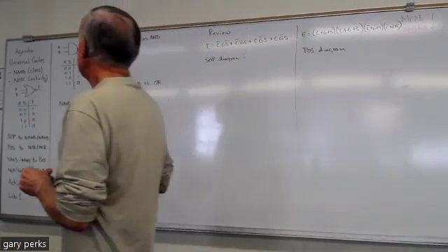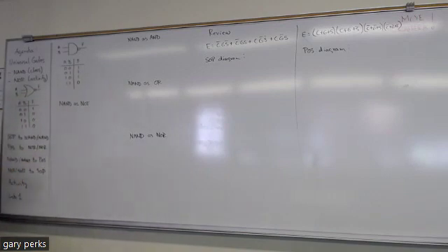So first of all, to understand how this is done, you have to refer back to the truth table for the particular gate. Here is the NAND that we're going to use in class. Here's the NOR that you'll use for the activity. So you may recall that with the NAND gate, you only get a 0 out when all the inputs are 1. It just takes at least one of the inputs to be a 0 to get a 1 out of a NAND. And again, it doesn't matter how many inputs you have, the same concept is true.